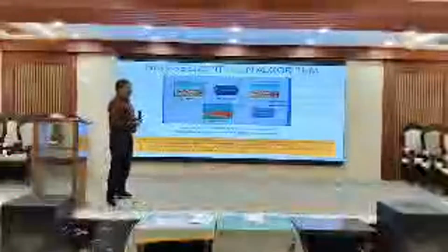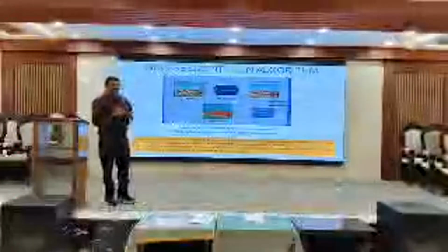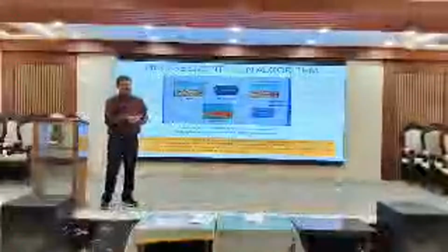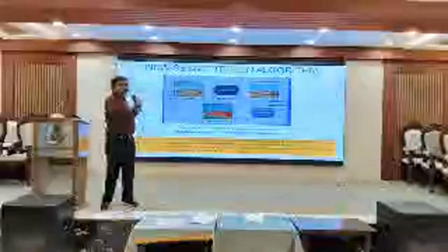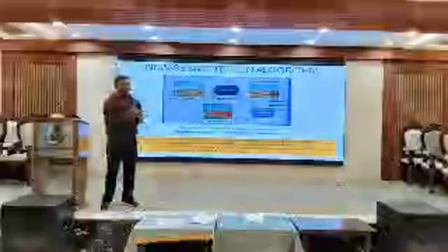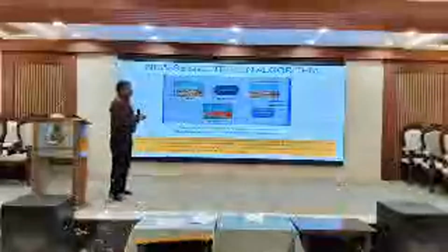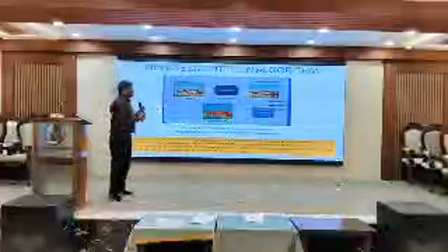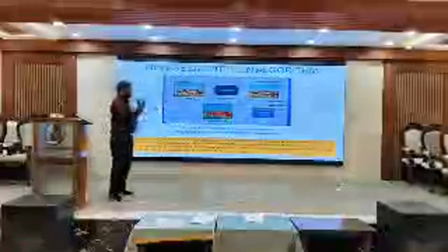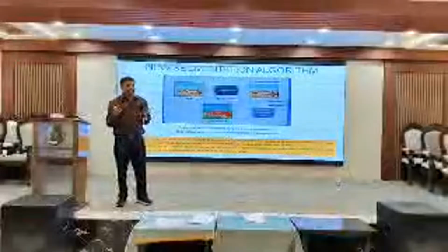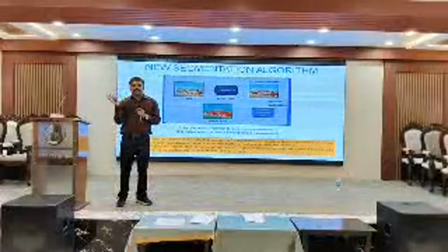So instead of going directly into segmentation, I try to do only supervised object detection, and then segmentation is done in an unsupervised way. This is the philosophy I work on. First I identify the region where the object is. Then I use the box as input, along with the original image, to the unsupervised model called the Segment Anything model, and then I predict the mask. This has been a major advantage because for me, cracks will be there, scaling will be there, different kinds of defects in concrete structures will be there.